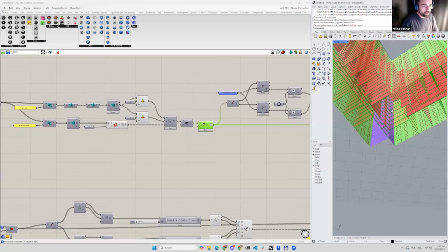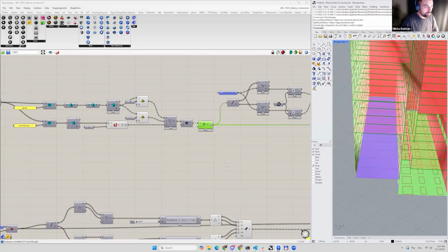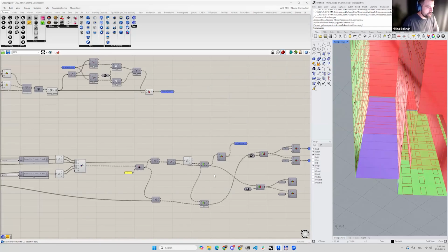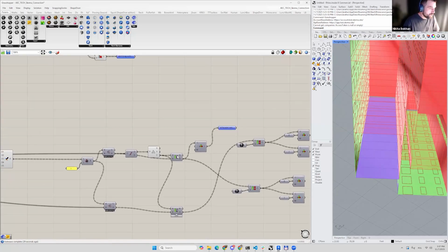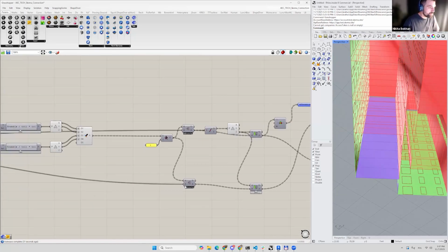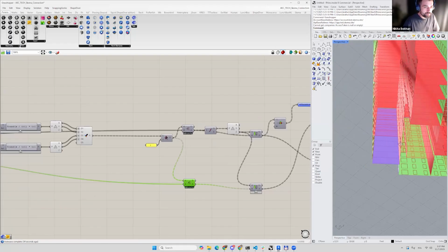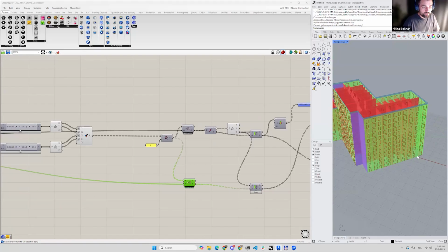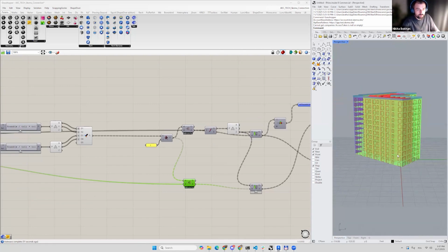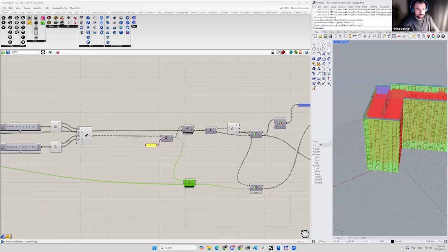So now we have all our interior and demising walls, and on the other hand, we have all our facade lines grouped by belonging to a particular facade. I group all the walls which have the same X and Y position in order to have this vertical stack of all the walls. My goal here is to have the surface of each wall.